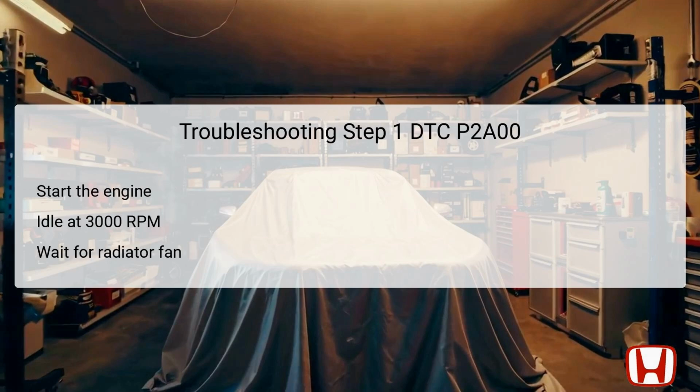The first step in troubleshooting DTC P2A00 is to start the engine and allow it to reach operational conditions. Set the engine speed to 3,000 RPM without load. This means the continuously variable transmission, CVT, should be in park or neutral, and if it's a manual transmission, it should be in neutral as well. This step is essential to ensure that the vehicle reaches a proper temperature and allows the components involved, including the AF sensor, to function correctly.